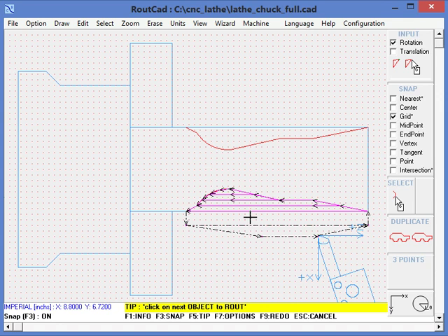But we have to keep in mind that if the very first routed location is the home location of the CNC, as in this case where there was a point here which was the first routed location, then even if the cutting head stopped at another location that is not the home location, when we reload the new G-code, if our CNC is set up properly, the CNC head should move by itself to the home location and then restart machining everything again.